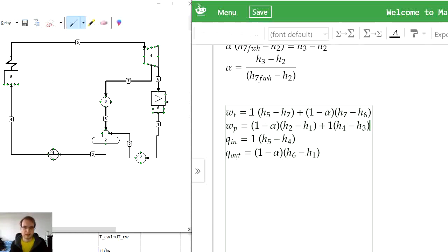However, this work input of the pump and output of the turbine, those are thermodynamic works, and the work of the turbine needs to be multiplied by the further efficiencies we have on the way, which are mechanical efficiencies corresponding to losses in bearings and so on.